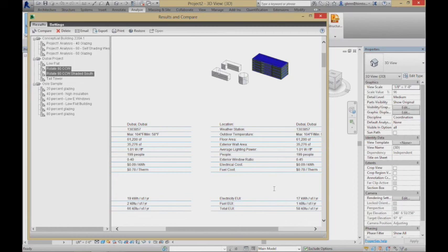So again, the point this is really trying to drive home is that simple little measures can actually make a very big impact. As opposed to thinking about having a bigger HVAC system or some very costly change, just thinking about putting a more interesting facade on the south side that has some shading could really save you more energy than increasing the insulation in all the walls, or putting in a much more expensive window glazing.